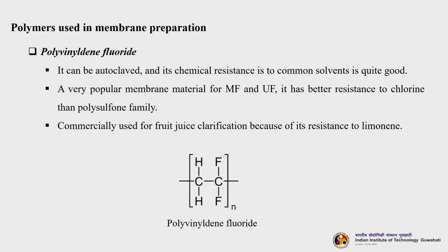So, the next class is PVDF, polyvinylidene fluoride. It can be autoclaved. This is the beauty of PVDF membrane, and its chemical resistance to common solvents is extremely good. It is a very popular membrane for manufacturing of microfiltration and ultrafiltration, and it has better resistance to chlorine than all other polymeric materials.